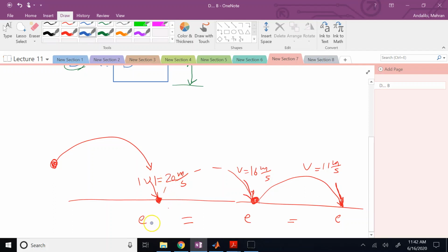Here you are hitting harder, so probably the first one is going to be maybe 0.5, then this one maybe 0.6, then this one maybe 0.7. Right? The easier the impact is, the smaller the velocities are, you're not going to deform as much, and E is going to go closer to 1. So ideally, E would increase as well. Maybe not this dramatically, but it does.